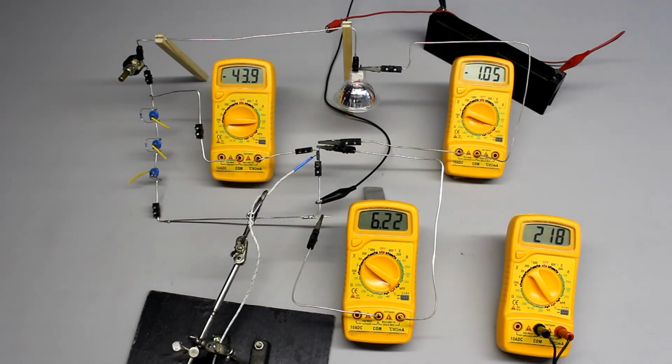The third method to destroy a transistor by ignoring the limit values is demonstrated by this arrangement. The BD135 is used to dim a filament lamp. With the adjusted base current of nearly 44 mA, we can detect a collector current of approximately 1 A and a voltage drop of 6 V at the device. Hence, 6 W of electric power are turned into heat by the transistor.